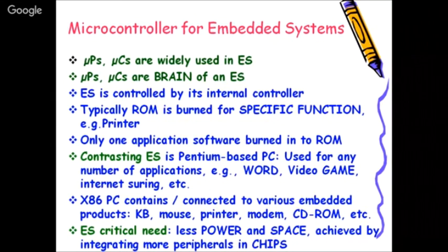These are embedded systems in themselves. There is a controller which resides inside. For example, in case of a mouse, the controller resides inside it. There is a PIC, a small tiny 8-pin controller, which resides inside the mouse, and that receives the commands from the CPU about the particular location of my pointer. So this connectivity is there. Each of these devices, whether mouse or keyboard, continuously communicates. When we press something on the keyboard, the ASCII code gets exchanged between your CPU core and the keypad.